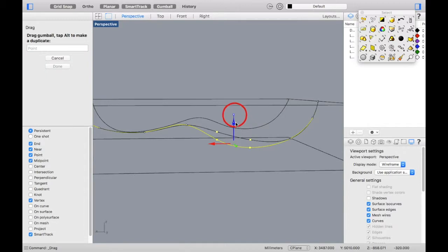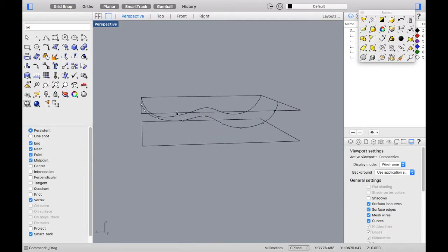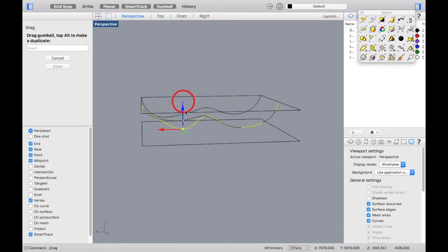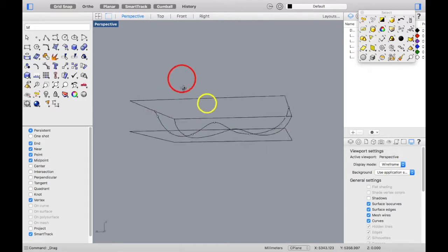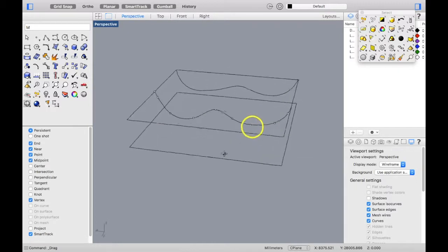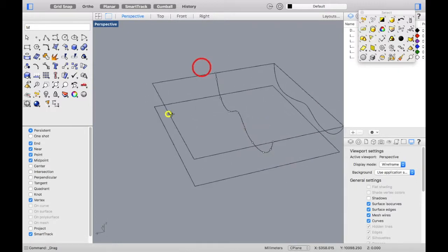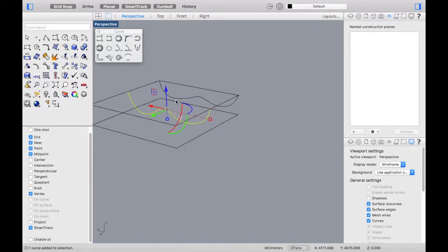So for that all you need to do is go and click on edit point, and the points on the curve appear. Since we used interpolate curve points, the points are on the curve, unlike the other option of curve, where the points aren't on the curve itself. So this helps you to get the precise editing.